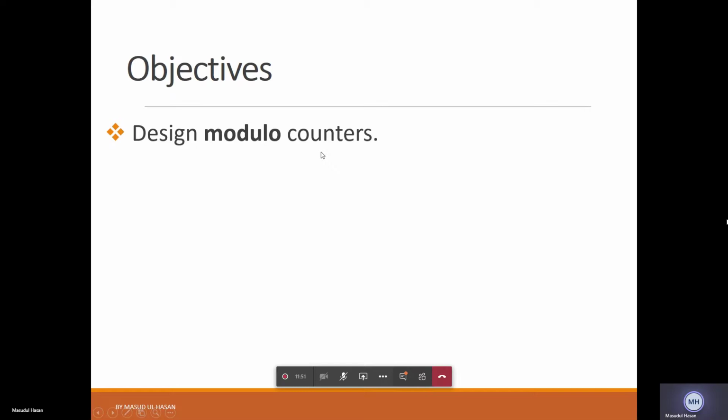Why do we need all the 4? Because we want to see all the digits from 0 to 9, and for this, we need all the 4 bits. We don't need the two outputs CEO and TC. So we need all the 4 bits. So a 4-bit output and a single-bit output CEO.